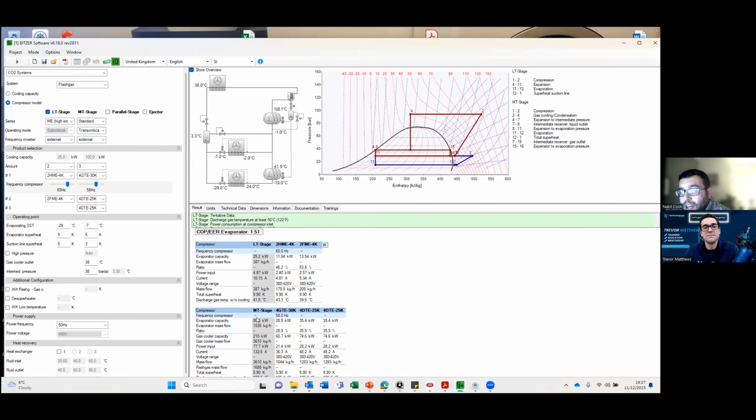Again, very, very close matching with those inverters. We have options on our MT side as well. So we have a design system compressor only COP here. By system, I mean comprising both the LT and the MT. I don't mean inclusion of fans or controllers or crankcase heaters. I just mean the amalgamation of both LT plus HT, but compressors only, of 1.51.